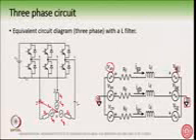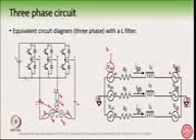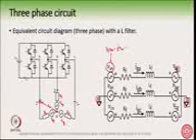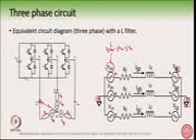I have shown you VAN, RF, LF and VAG. And this VAN is 2/3 VAO minus 1/3 VBO minus 1/3 VCO, and VAO is again a combination of SA times VDC. SA can be 1 or 0. So this is how the chain forms.